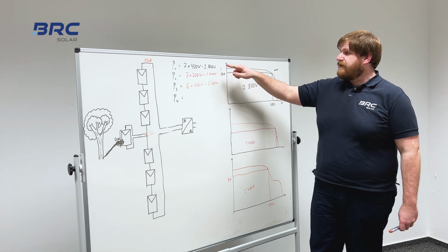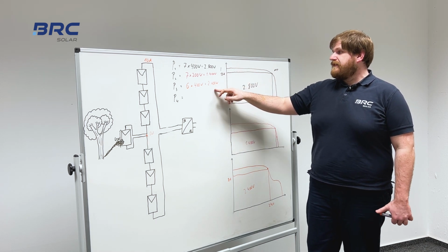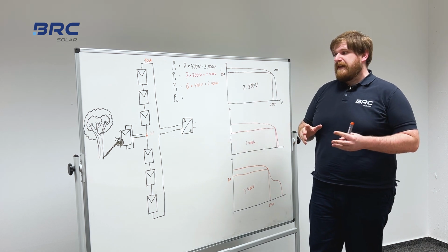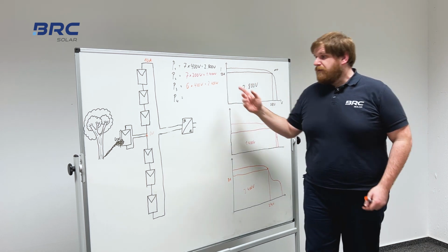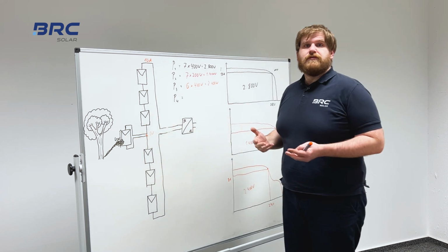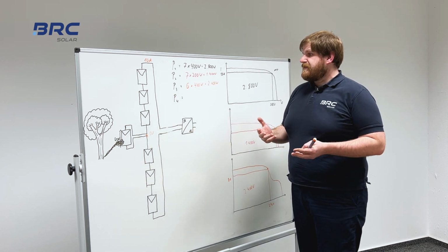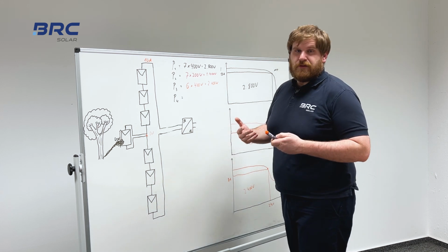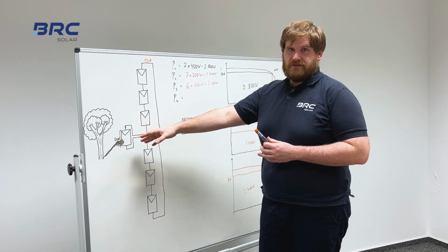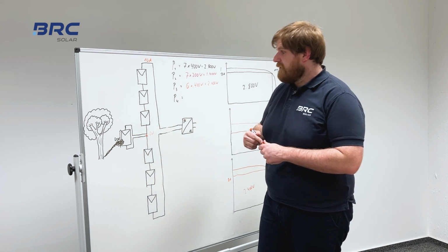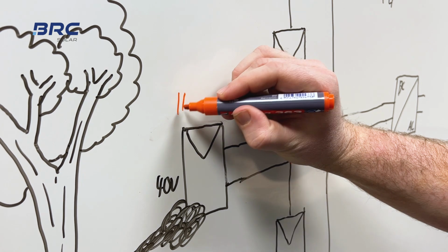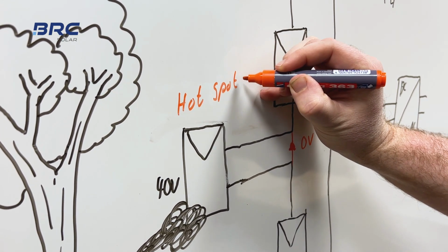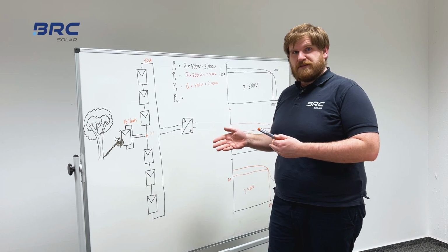So if you look just at the power, we see that this scenario is much better than the one before. But we have still energy left that is missed right now. We saw before that this one module could produce 200 watts, and this energy is lost in this scenario. Even worse, it's not just lost, it will be transformed into heat on this one module. So over time we have hotspots here on this one module. And over time this one module could be destroyed because of these hotspots.